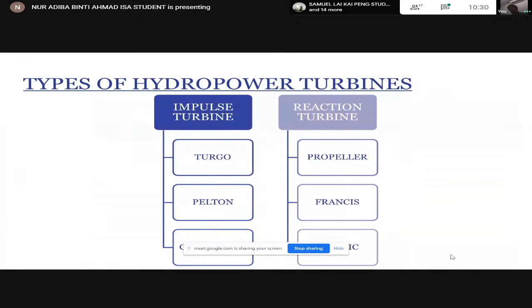We chose impulse turbine, which has pros and cons, and there is also research saying that even though the power generated can be used for other turbines such as cross flow or Francis, the Pelton turbine can also be used with a head of 15 meters.